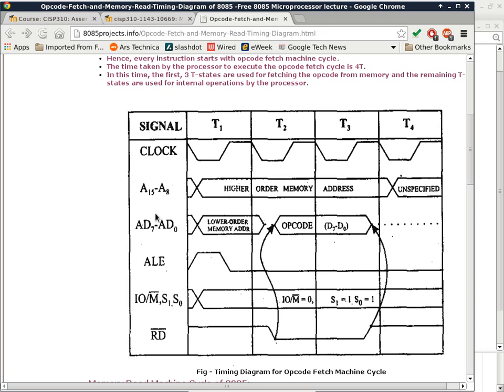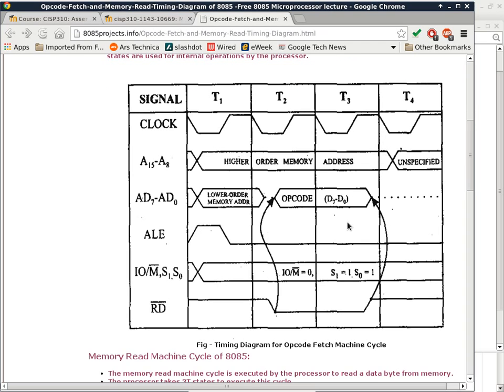All right. So getting back to this picture here, this digression was only because of the discussion of why we have to share pins between the address bus and the data bus. It's because of limited routing resources. When you only have a 2-layer board, that is already a lot of pins, a lot of traces to route.